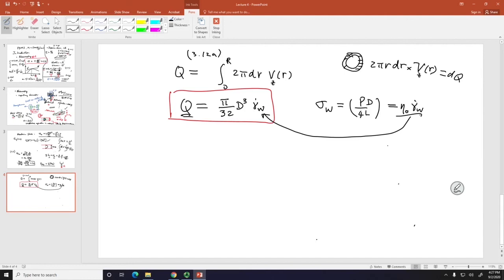Predictably. So for a Newtonian material, this capillary can be a way to measure viscosity, for example. That's what I'm trying to say. Because as soon as you determine your Q, knowing your pressure, this eta is given in terms of those two quantities, just like the Newtonian law should. Okay, so this is the part that I wish to go through. Any questions?